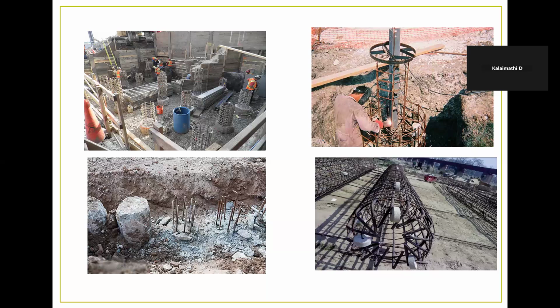And there are other types of sheet piles also, which we have seen already. Those are vinyl sheet pile. It is an effective alternative to steel sheet pile for bulkheads, sea walls, and cutoff walls. They're also superior to alternative materials like concrete and wood. The main advantage of vinyl sheet piles is the superior corrosion resistance when exposed to sea water and no oxidation occurs.